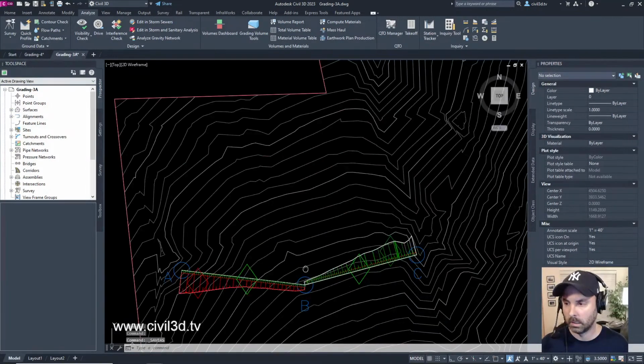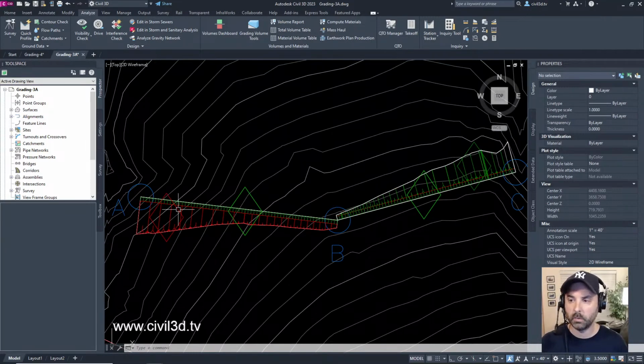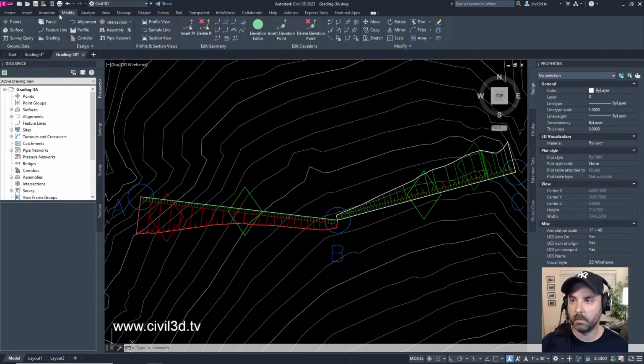Okay. If you remember this, we're creating our gradings with this for our ditch. If you remember the ditch exercise. Okay, editing the grading criteria. In this exercise, you will edit a grading criteria and an associated grading adjust to reflect the criteria change. You'll edit grading criteria attributes values in two ways. Number one, in the elevation editor dialog box, which that's what we've been dealing with right here.